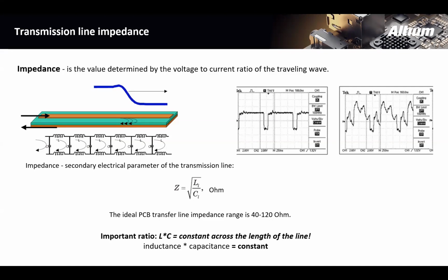Now, when you have an impedance mismatch, you get reflections, and that's what we're seeing manifest here in these two oscilloscope images. We have the signal as we really expect it at the receiver on the left, and we have the signal as we actually encounter it on the right. You can see some of the original signal in the image on the right, but there are a lot of reflections that occur because of the mismatch of impedance, and because the impedance that the signal sees is not to the specification of the transmitter and receiver. Again, just in general, your impedance equals this equation we have here: the square root of L over C.